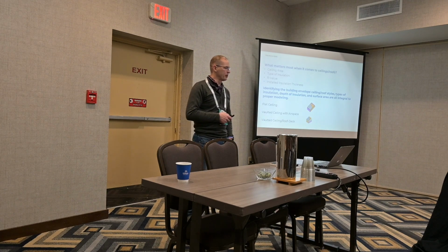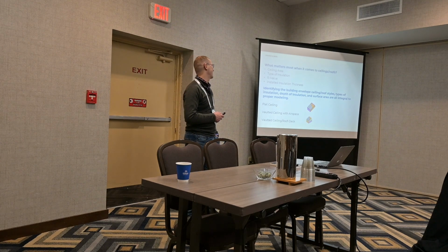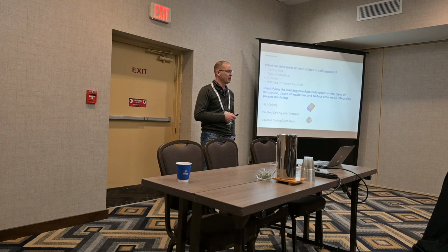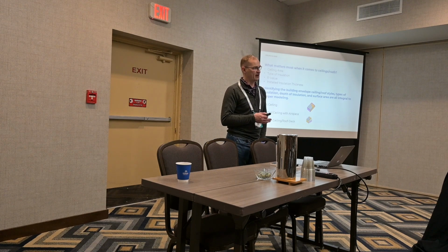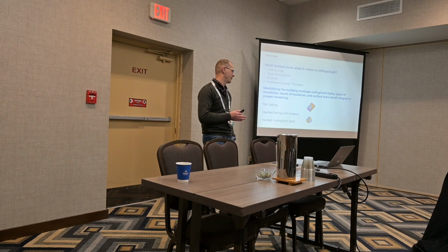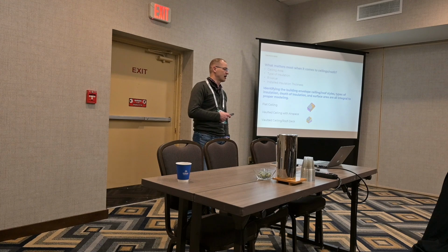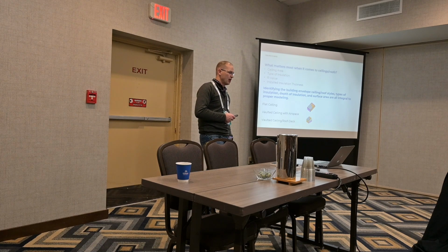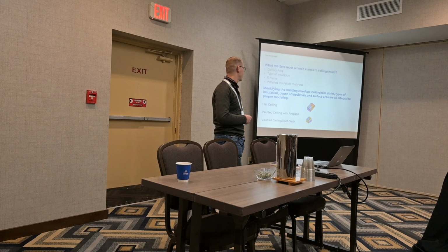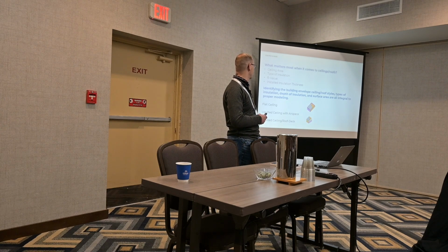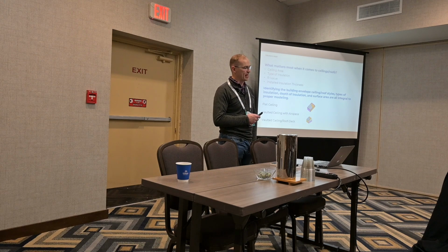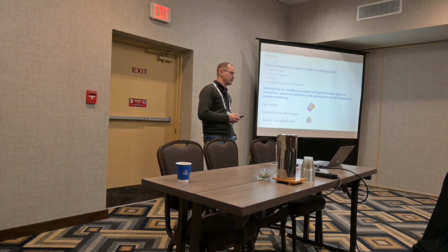So moving on to ceilings and roof. For ceilings, ceiling area, types of insulation, R value, and then the installed insulation thickness. And as you can see, most of these are very similar between any type of area that has internal insulation within the studs. Identify the building envelope, ceiling roof styles, what type of roof it has, whether it has insulation along the roof deck or within an attic space, but it is important to make sure you catch that. The flat ceiling, vaulted ceilings, how air moves through that space is affected by that and does impact the Manual J.